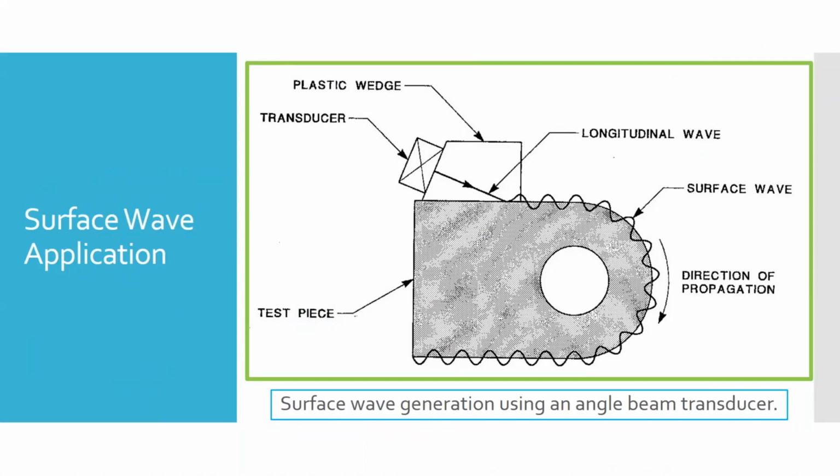The tester is going to time how long it takes for this wave to travel around and reach a back wall. Then that's going to bounce off the back wall and make its way back to our tester. Okay, so it's a pulse echo. It's a pulse echo shear wave running along the surface, and so it only goes by that surface wave property.